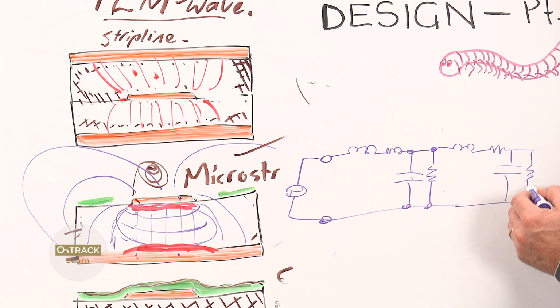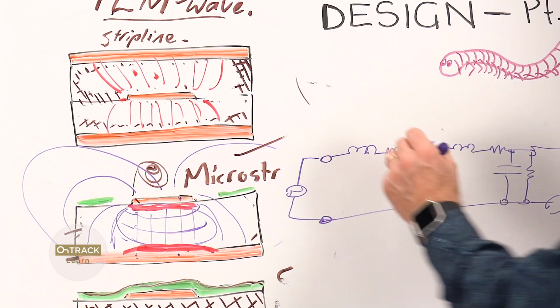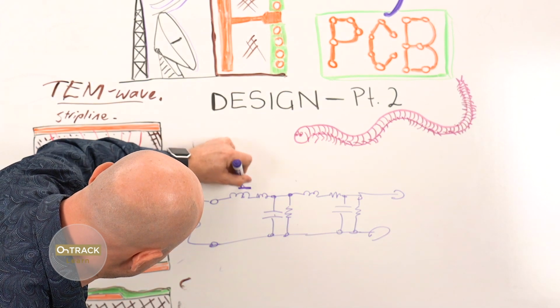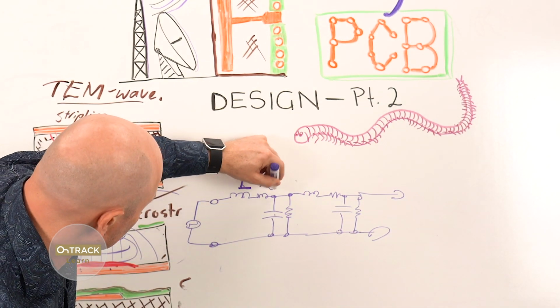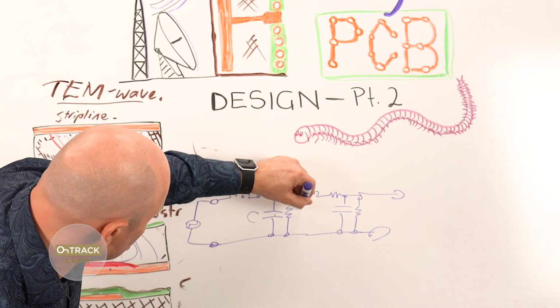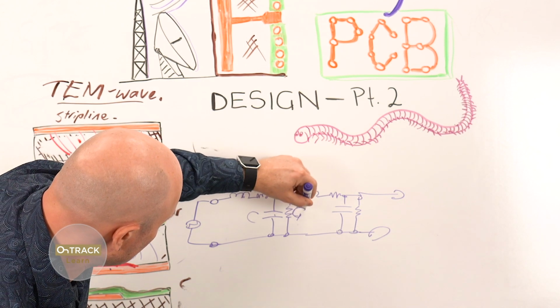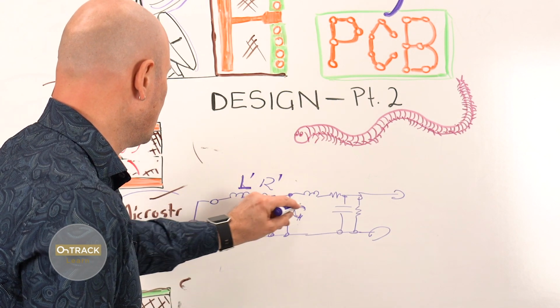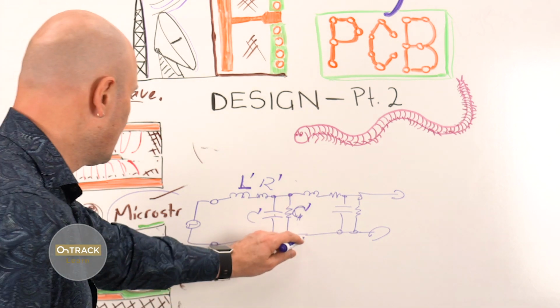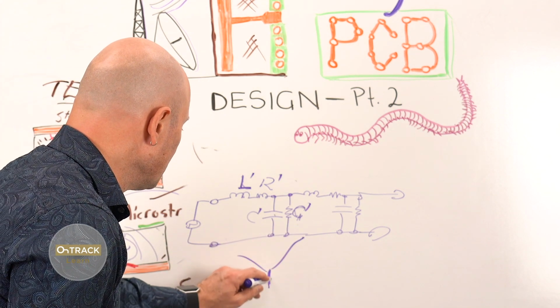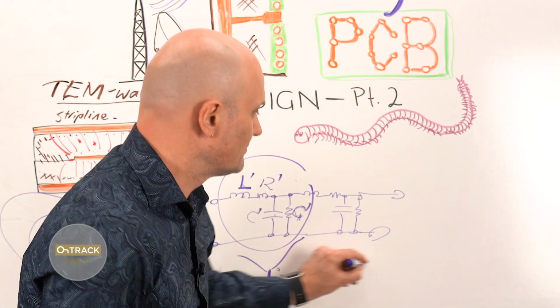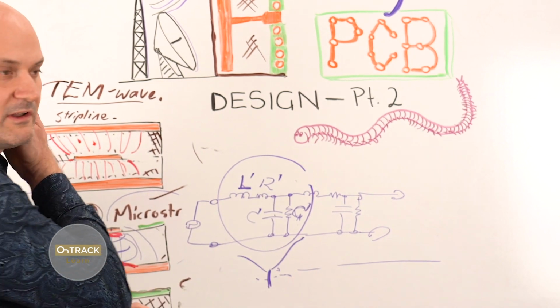And so we have this concept of inductance, L. That's a wonky L, let me do that clearer. Series resistance, capacitance, and conductance, G. So we have this R, L, C, G, and those infinitesimally small sections of circuit join up in series to form a whole transmission line.